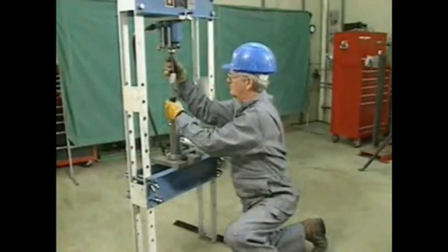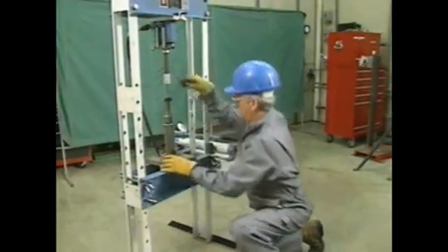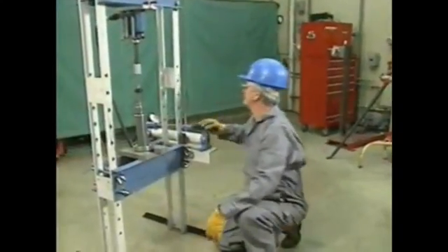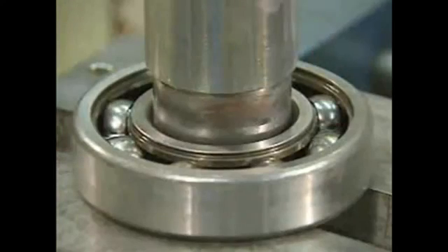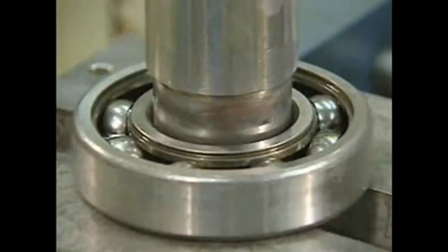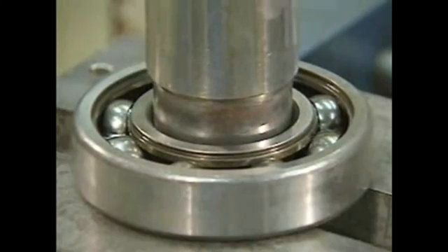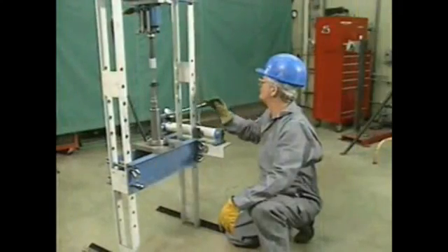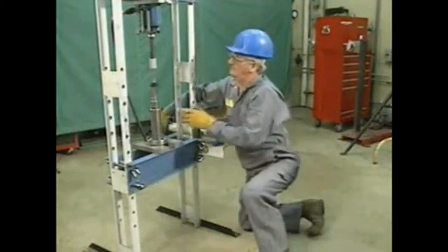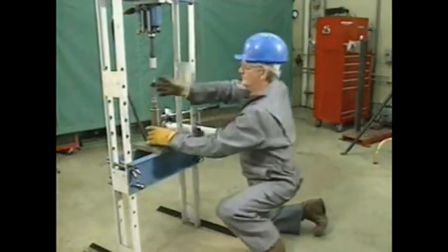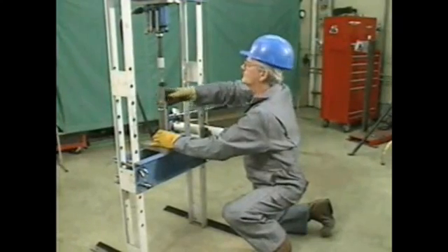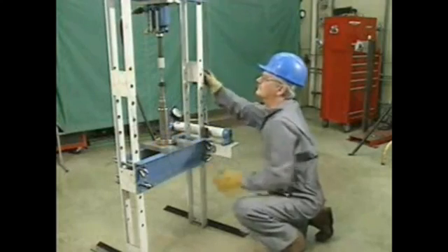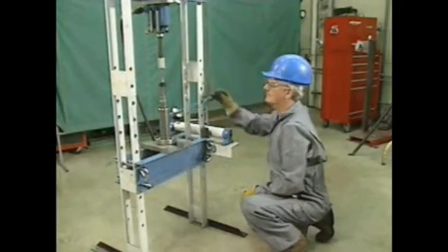Before operating the press, the mechanic checks the whole assembly again to be certain that everything is lined up properly. The mechanic then operates the press. He watches the shaft carefully to make sure that it moves smoothly into the bearing. If the shaft does not move smoothly into the bearing, the mechanic must stop the press because the bearing might be jammed. If this happens, the mechanic must correct the problem and then recheck the alignment of the bearing, the shaft, and the ram. He can then restart the press.